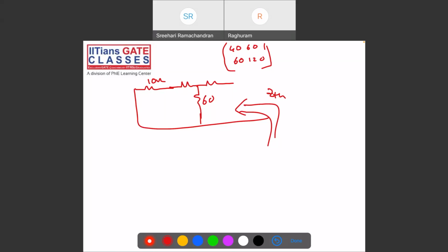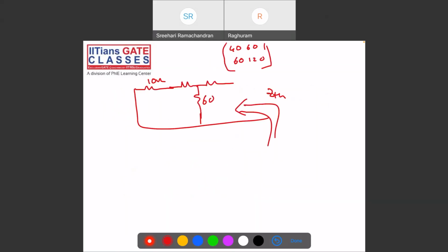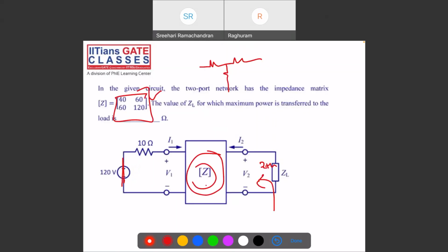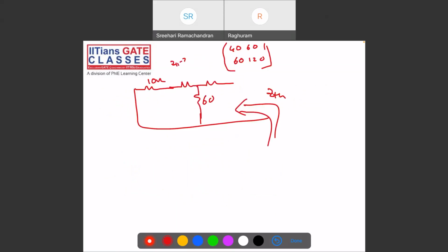No. I said this is Z network, right? Yes, Z equivalent. I know the T of this. See, if I have a T equivalent, can I write down the Z value? Earlier you were told that formula Z11 minus Z12. Yes, this is Z11 minus Z12, Z22 minus Z12, and this is my Z12. I have Z12 directly 60, so this should be equal to Z11 minus Z12.